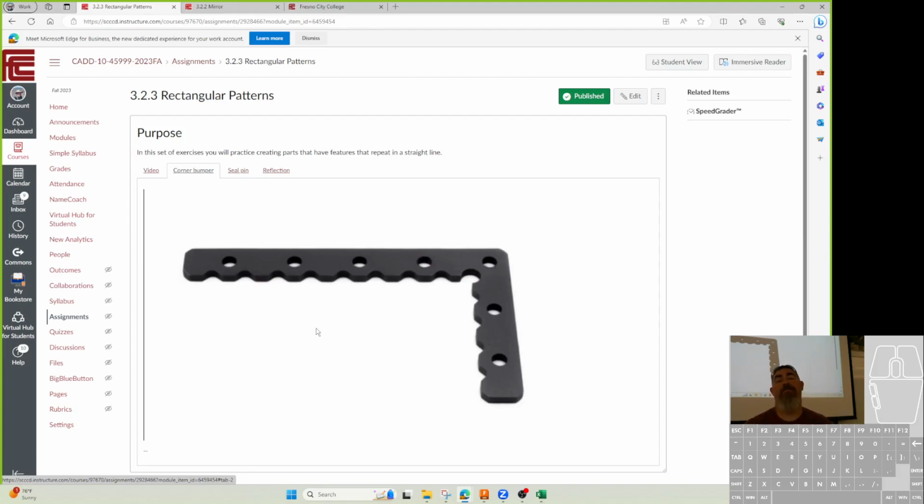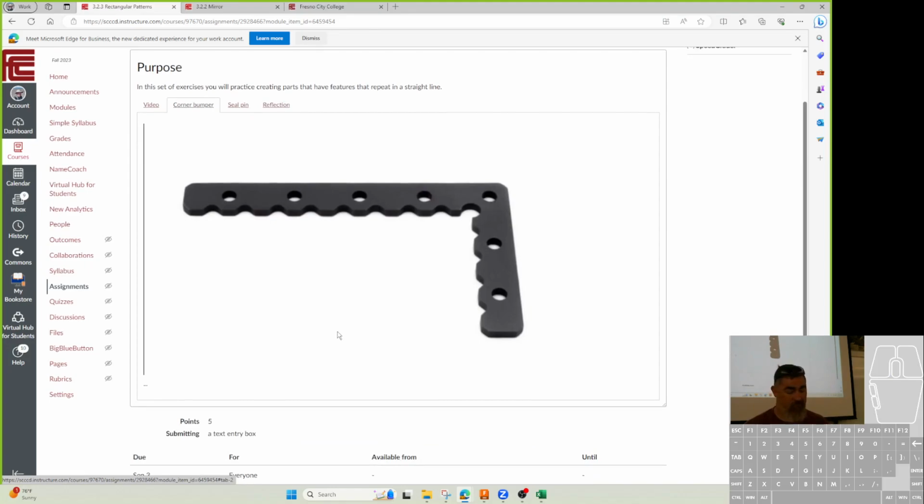Makes it easy. I imagine a keyboard is probably also done with a lot of rectangular patterns. Yeah, that's not a centered one, but you create a hole, one key there, and pattern it over. Because it has the offset, you probably pattern the row, make the next, or create the QAZ keys and then pattern those across. Each of those could be its own cut feature, and then you pattern all four of those features across. That way you have space to do your other things.